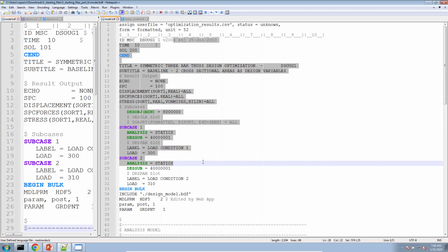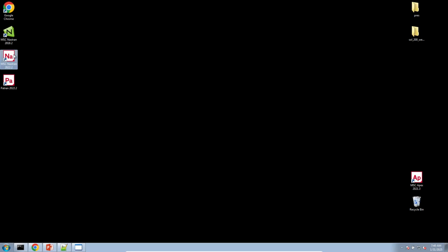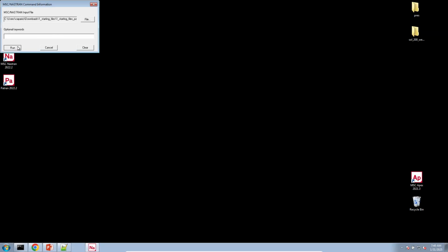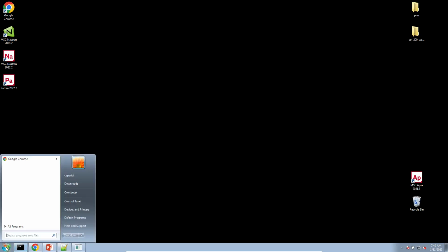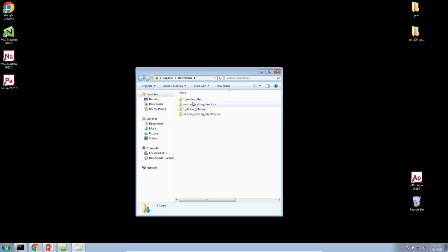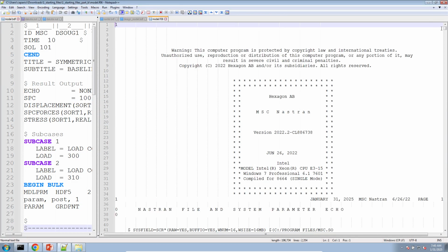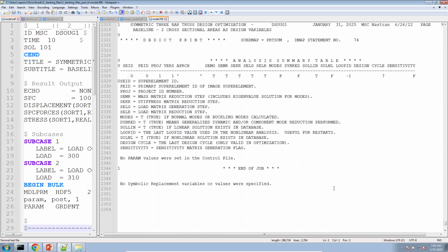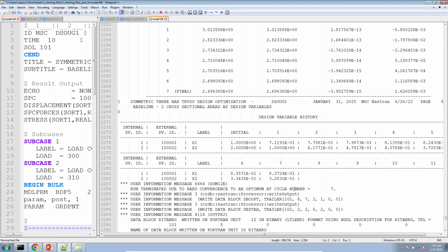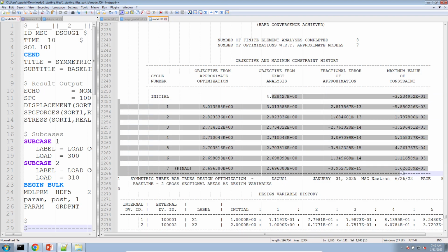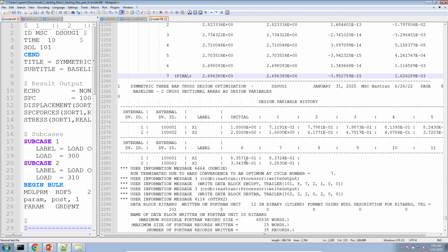So here, let's assume you already have those bulk data files. You would run Nastran to perform your optimization, and you would get the F06 file that contains the result of that SOL 200 optimization. If we look here at the very end, we should have information about the SOL 200 solution. Here you can see we've minimized the mass, the final design is feasible, and in this 7th design cycle, we get the SOL 200 solution.